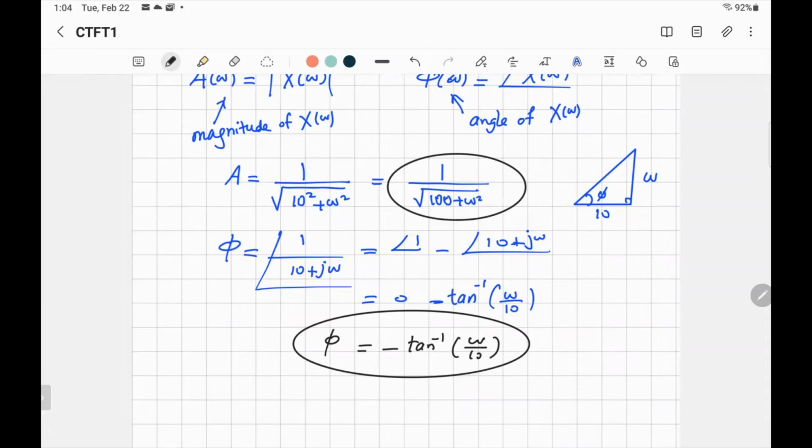So now we are preparing to find the content of a signal with different frequencies. You'll find the spectra, the amplitude, and the phase. To do that, it's better to write a program and substitute values for omega from -50, for example, to +50, with a step of 0.01, not 1 like in Fourier series. Why? Because it's real, so you want to find every single point to get a smooth curve. But here in class, if I substitute 0.01, I will spend the whole class just taking samples.